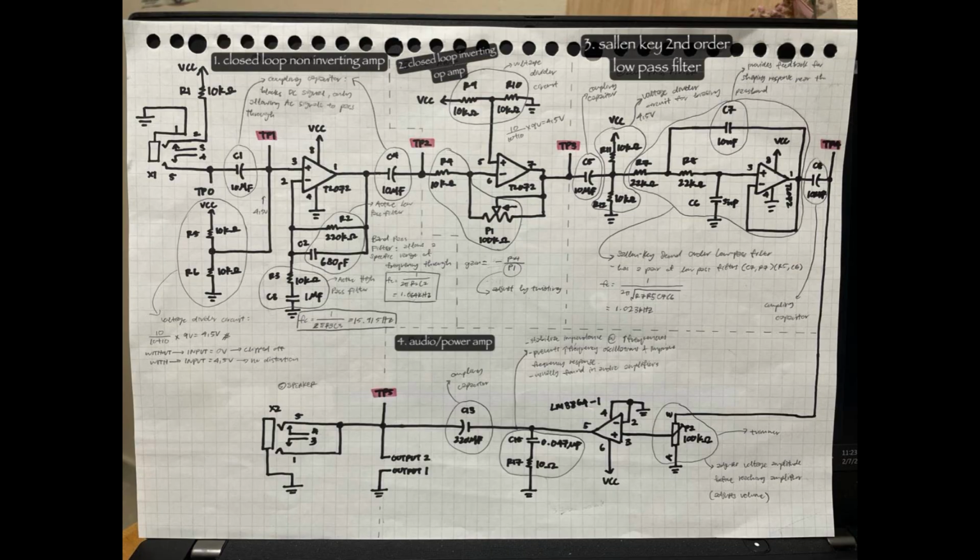I didn't record my waveforms for this, but a huge mistake I made when I was doing my measurements was that I constantly moved the function gen for every stage I measured. So at first, I didn't know that the function gen was supposed to stay at C1 the whole time. So I kept on moving it to the next test point as I kept on testing each stage.